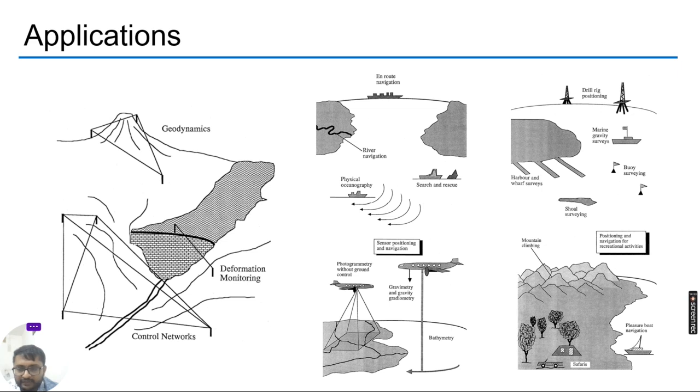And then we will find the velocity by taking the difference between the readings and dividing it by time. Like that we will find out the velocity of the particular locations, and how much displacement is happening and how much time it will take, or how much pressure the water is exerting on the reservoir or dam. Like that we can study. Apart from that, you can also do this kind of study on various bridges as well.